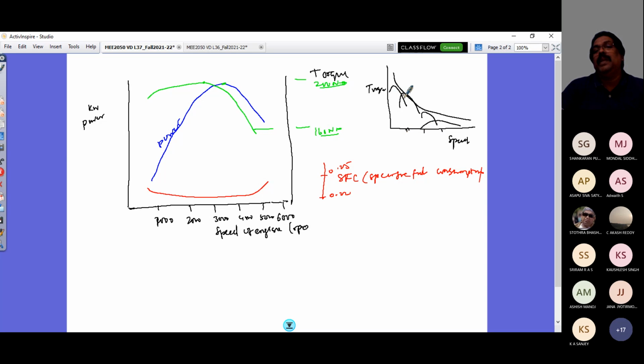So for the next range of speed, the characteristic of this is like that. So when I have my engine characteristics in intermediate ranges like that, this is at the lowest gear. If I provide an appropriate transmission to take care of the output of my engine and to take that motion to the drive axle, I would have this in first gear, and this is higher gear or the last gear.